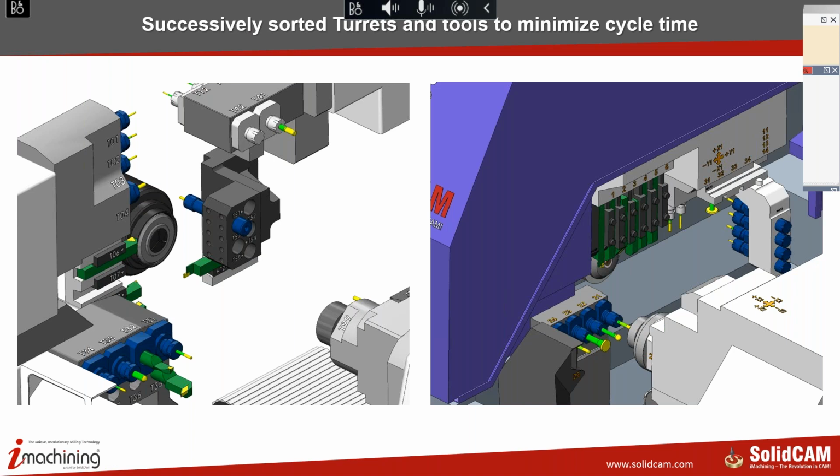But basically, what I wanted to present here is that these machines always work on the main spindle and on the back spindle simultaneously. So the goal is to pretty much set the same machining time on both spindles in order to minimize the cycle time. Yes, so both spindles work, let's say, roughly the same amount of time. So the software must be capable to define all the tools, to define all this kinematic, to be able to see the two targets, two stocks on both spindles, and to minimize the cycle time.